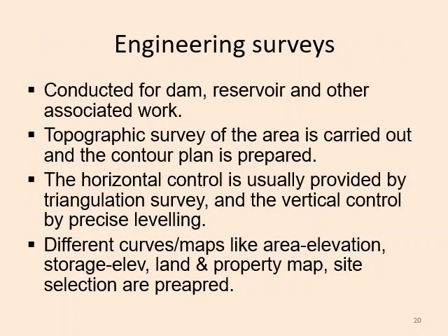So first is engineering surveys. The survey work will be conducted for the dam, reservoir and other associated construction work. A topographic survey of that area is carried out and the contour plan should be prepared first.